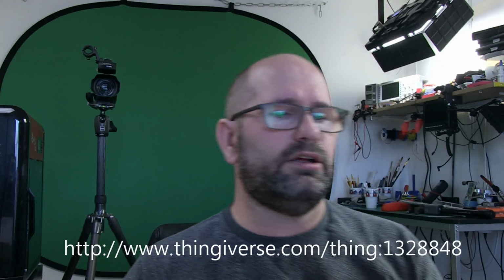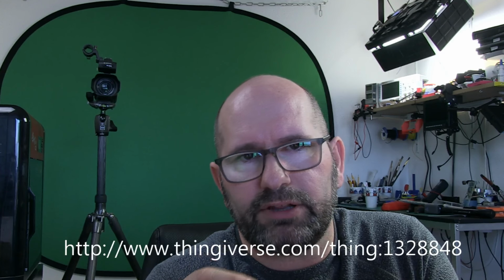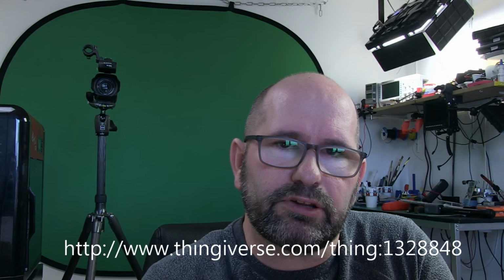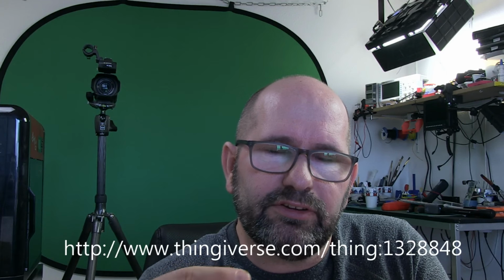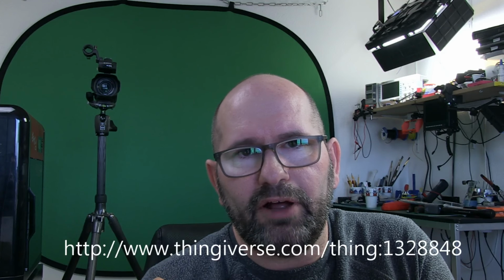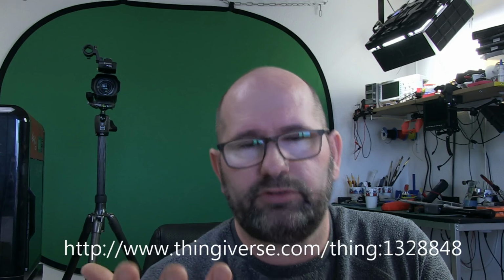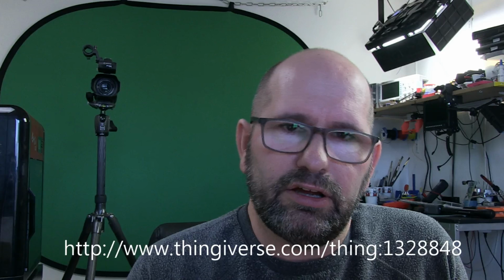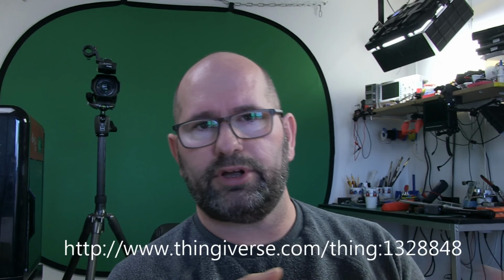So the key to overriding temperature limits is Simplify3D and this tube. With Simplify3D you can go high, and if you go past the 260 degrees Celsius range, then your PTFE tube, which is inside the nozzle, is going to melt. So stay under 260 degrees and you can do it with the normal hot end. If you want to go over that 260 degrees, then you will need another way of working around it.